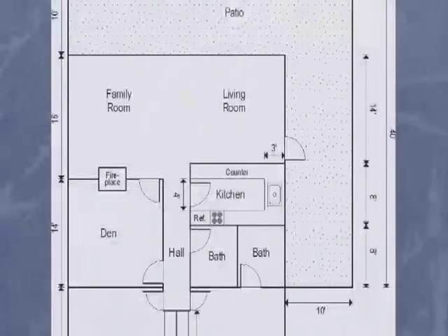To figure out the next dimension, we know that across that fireplace wall up to the hall is 14 feet. And if we go up to the end of the counter, look on your plan there, up to the end of the counter, we will have gone across the same width as those two closets toward the bottom of the page. So we will have gone another 2 plus 2 feet, another 4 feet. Now we are at 18 feet. So we can put 18 feet as a dimension. You can write it right in on the plan, and that gives us the size of the living room.